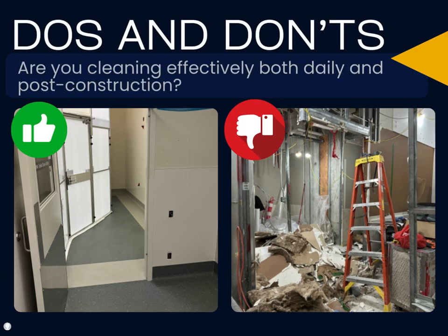Are you keeping the work site tidy on a daily basis? Have you done a thorough post-construction clean? Construction cleaning is an ongoing process of cleaning that happens throughout a construction project, not just at the end. Its main goals are to keep the site clean on a day-to-day basis through scheduled daily cleanups, prevent dust and debris from building up in fixtures, ceilings, service spaces, and other hidden or enclosed areas. By making cleanliness a continuous part of construction rather than a final step, we greatly reduce risks from dust, debris, and contamination, creating a safer, more compliant work environment.